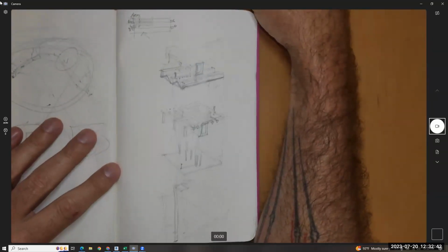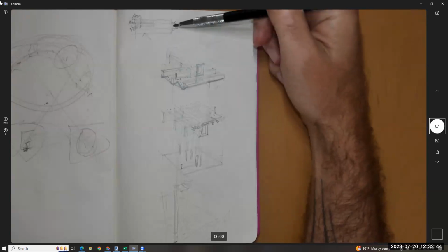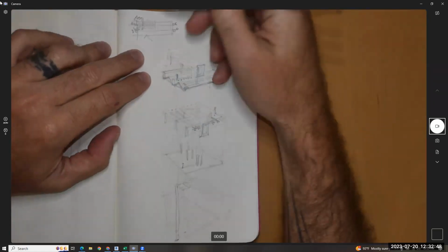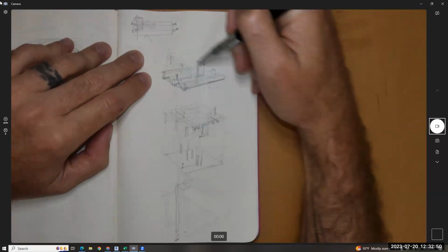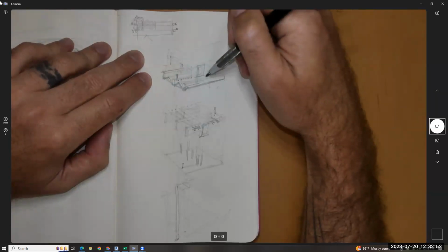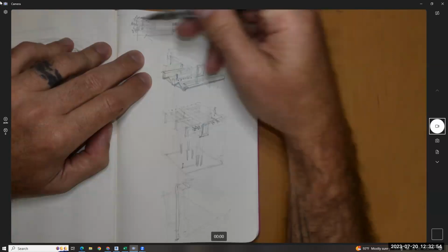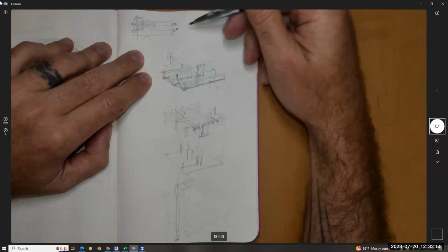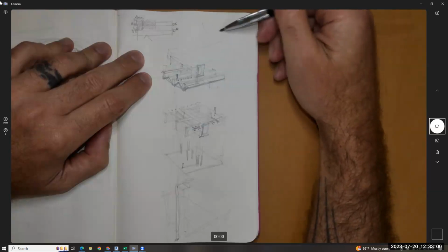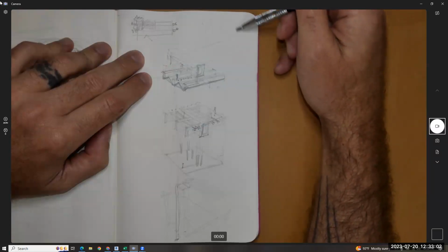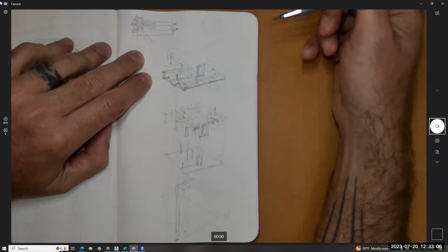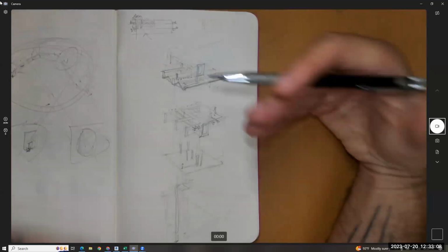Yeah. Okay. That idea of showing us the plan and showing us trib area, maybe the square footage, and then showing us the axon so that we understand that this isn't the trib area. That's just maybe a smart way of showing that. Sometimes it could be the whole trib area. Sometimes, you know, a couple of you guys did, if you've got a nice simple project and it's a bay that's repeated and you show a little plan and just show that bay is what you've done, that's a great way of doing it. So there's lots of ways of doing this based on the project.